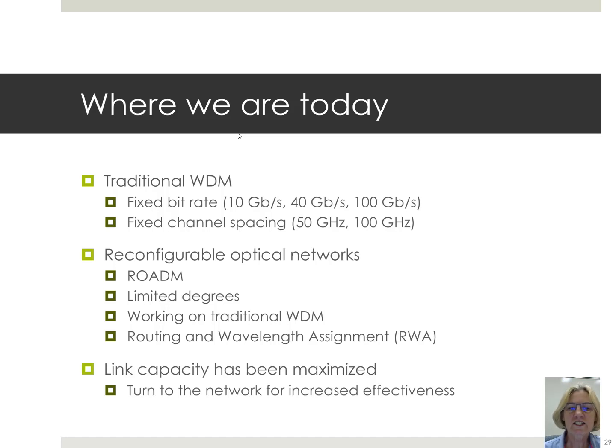We also have fixed channel spacing. And using dense WDM, we have either 50 gigahertz spacing or 100 gigahertz spacing, depending on the system we're looking at. We have reconfigurable optical networks today using ROADMs with limited degrees in these ROADMs.